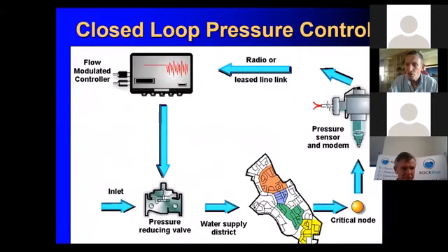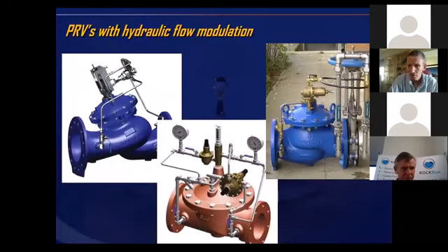What's important to realize here is by adding that device at the critical point, you now have another widget in the chain of events that can go wrong. So depending on how good your technical teams are and whether things are getting stolen, you may find that in certain cases the appropriate technology is the basic fixed outlet control. You can go for a number of different types of controller. You get hydraulic controllers. There's a couple of hydraulic controllers. Most valve manufacturers have their own hydraulic controllers.